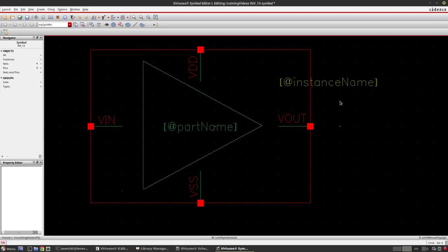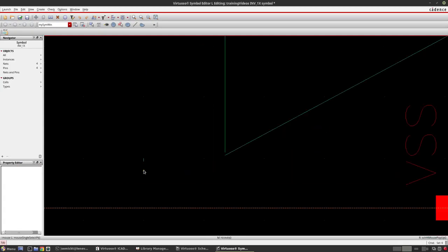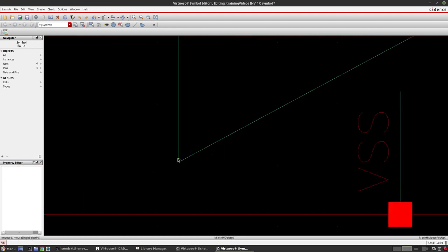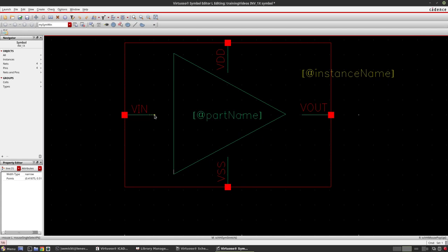Right, so yeah, I think this one was... so what I will do is I will select this point and extend it. Select this point edge and click on M, then you can easily extend it. So similarly I will extend it.